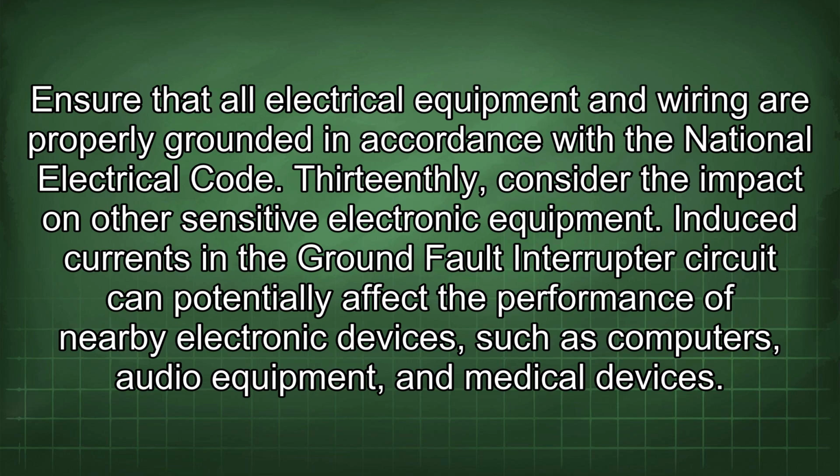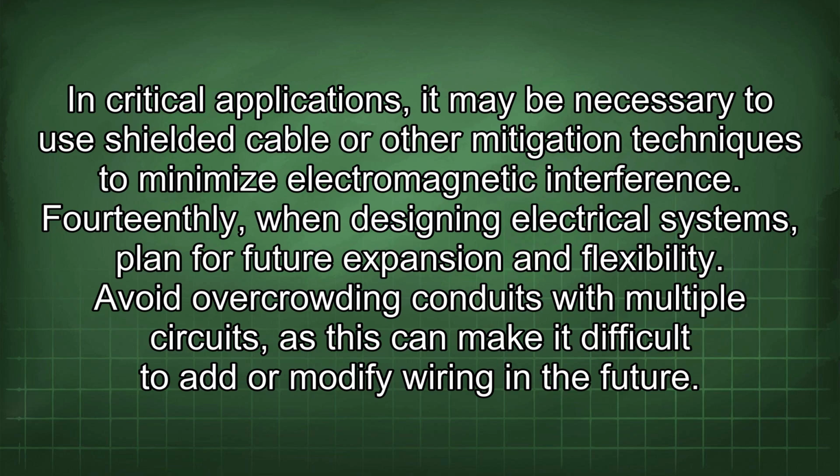13th, consider the impact on other sensitive electronic equipment. Induced currents in the ground fault interrupter circuit can potentially affect the performance of nearby electronic devices such as computers, audio equipment, and medical devices. In critical applications, it may be necessary to use shielded cable or other mitigation techniques to minimize electromagnetic interference. 14th, when designing electrical systems, plan for future expansion and flexibility.